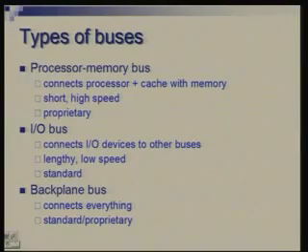Now if you look at a system like the Pentium 4, there is a concept of what is called a motherboard, and there is a bus running on that. That would be something like a backplane bus, but physically it is not a backplane bus. In a logical sense it would be a backplane bus on which many boards could be plugged in, with the difference that you do not have a processor board or memory board plugging into that. So it's more for input output.